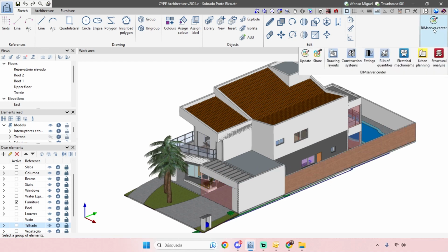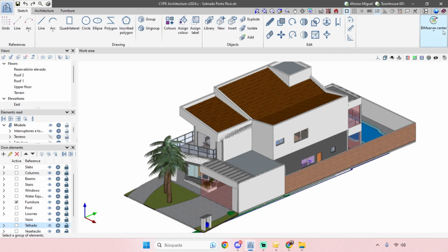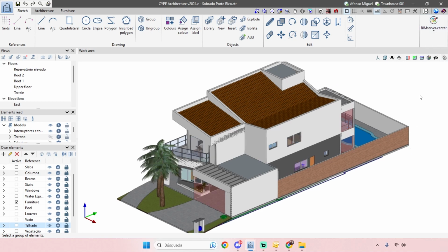to then use the options that we have here to share this project, to generate this IFC file, and then share it with someone that will be working with us in the same workflow. Okay, so this layers system is quite simple, but it's very useful. Okay, just showing here that inside of a layer, you can have different elements, according to the IFC categories of the elements that were modeled, so you can also activate and deactivate the elements inside of a layer.